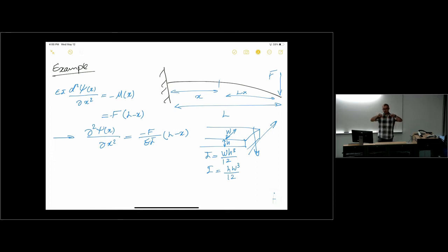If you hold them together very well, ideally glued, and on top of each other, they become 8 times harder to move downwards. So the moment of inertia for this situation is this. Let's call this Iz and then Iy. This is deflection in the Z direction, that's in the Y direction, for example. So just keep that in mind. It's WH cubed over 12 with H being the thickness in the direction that you're applying the force.